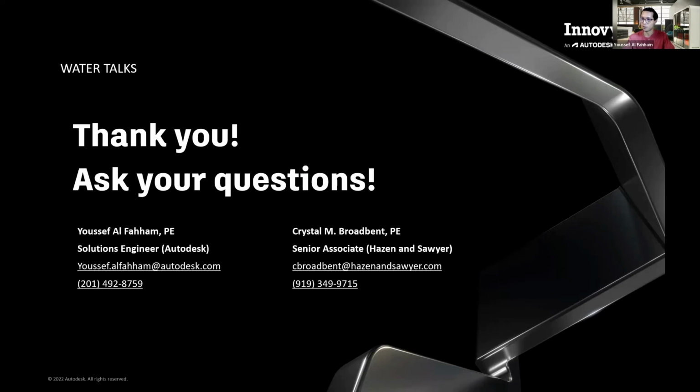But then there was another question on recommendations on pipe segment lengths used. Yeah, I usually start with 10 as my default. For larger systems, especially when I'm calibrating, if I have data that I like and I trust, I can go up to 30, 40. But we've done sensitivity, like we took a model and played with both the cavitation values and the pipe segments. The larger the pipe segment length you use, the more dampening you will see in your pressure waves. So that's why you want to keep it on the shorter end if you can and have the capability, and the runtime is not a problem for you.